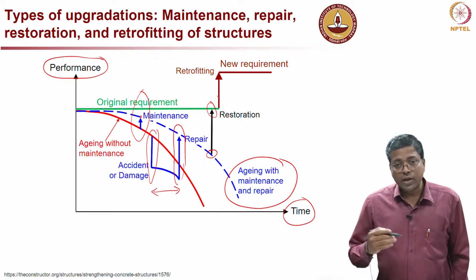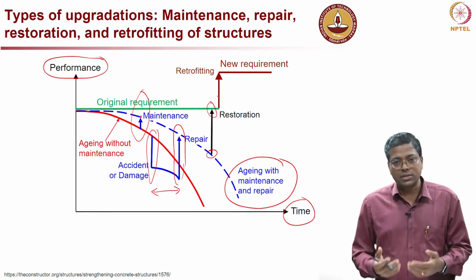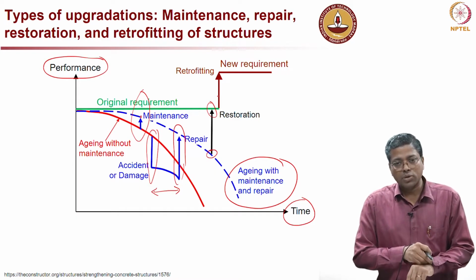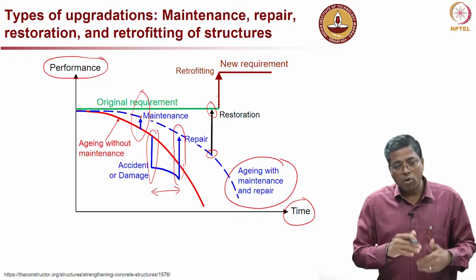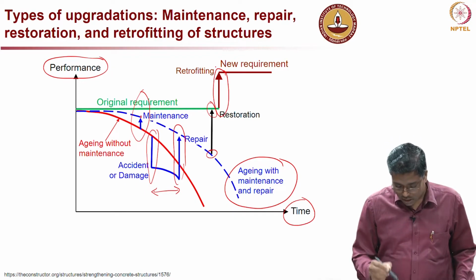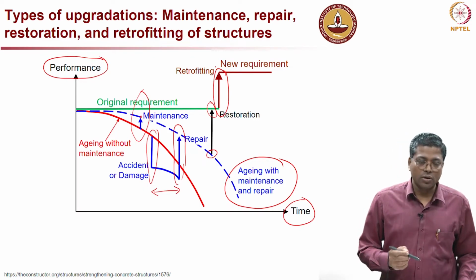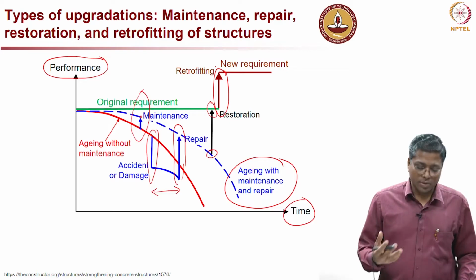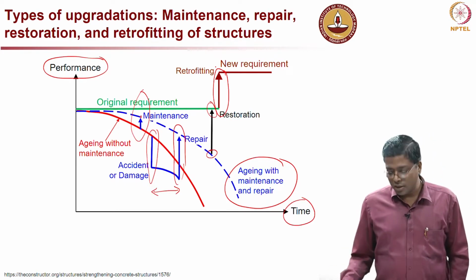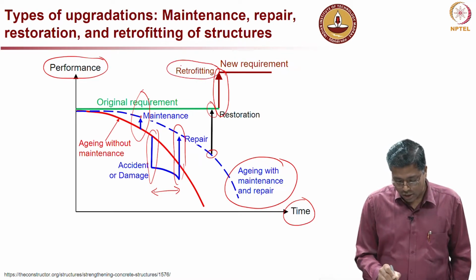Then if there is another reason for retrofitting, to increase the capacity or performance to a point which is more than the original requirement, then we go for this arrow here, where we enhance the strength further or improve the properties further, so that you can get higher capacity, and that is when we call retrofitting.